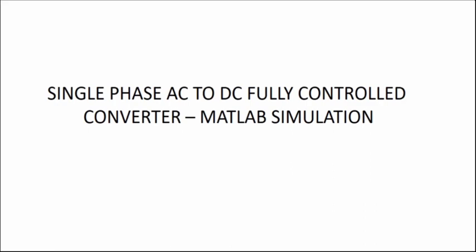In today's session, we are going to see the MATLAB simulation of single-phase AC to DC fully controlled converter. In single-phase fully controlled converter, single-phase AC supply is converted into a regulated DC voltage, wherein the output voltage is controlled by adjusting the firing angle of the thyristors.